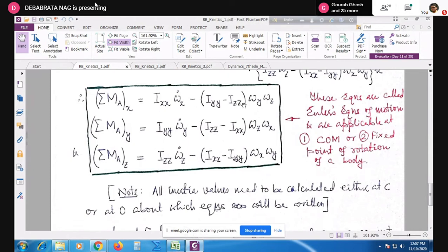Because the xyz axes become body fitted, the body and the reference frame do not have any angular relative motion. As a result, the orientation of the body with respect to any observer at this xyz reference frame will be constant. So in that case, the time variation of the product moment of inertia terms can be avoided.